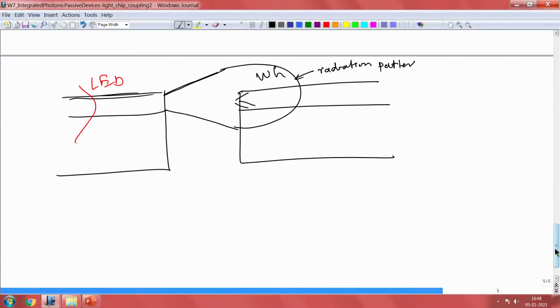So, the way to look at that is you have an acceptance angle here, right. So, there is a cone here. So, there is an acceptance cone, only within this cone you are going to get all the light propagate through the system, otherwise the rest of the angles are going to be radiated. So, all this is radiating outside. So, you should have this particular angle here for it to propagate. So, again whatever total light available from the LED here may not couple into the waveguide here.